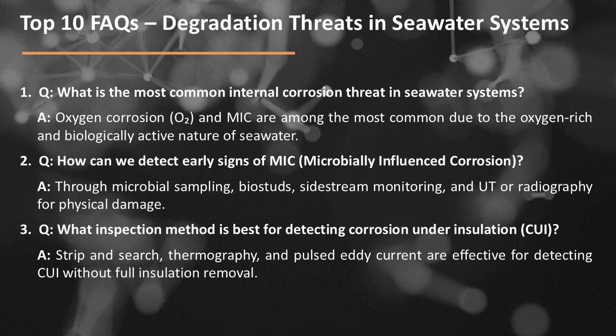Question number 2. How can we detect early signs of MIC or microbially influenced corrosion? Answer: through microbial sampling, biostuds, sidestream monitoring, UT, or radiography for physical damage.